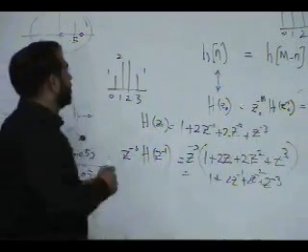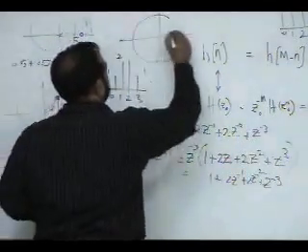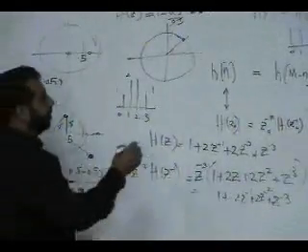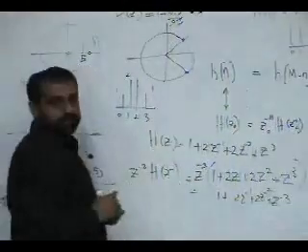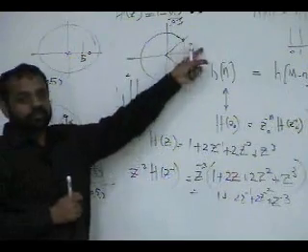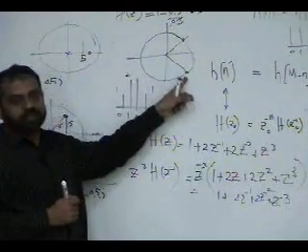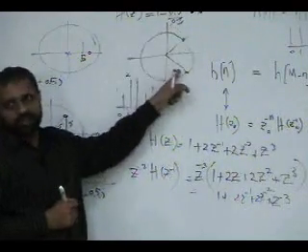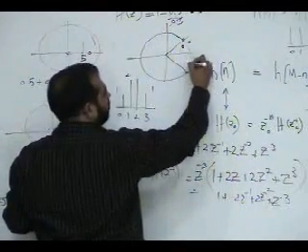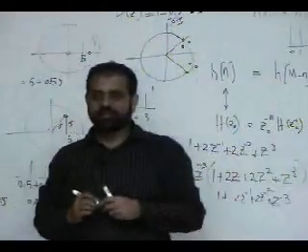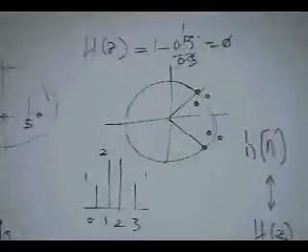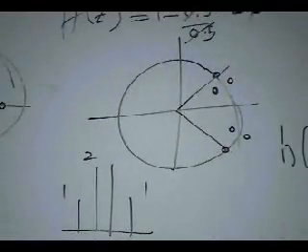Okay. Obviously, if there is a 0 here, where will be another 0? Because its 1 over this will be, if its magnitude is 1, it will be here, but just a conjugate here. A 0 on the real axis will only have a 0 here, but a 0 here will have 4 of these. Okay, so let me go and show you the MATLAB design tool and see how the zeros are placed.